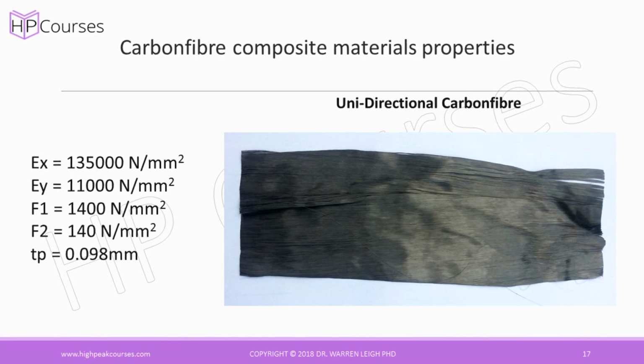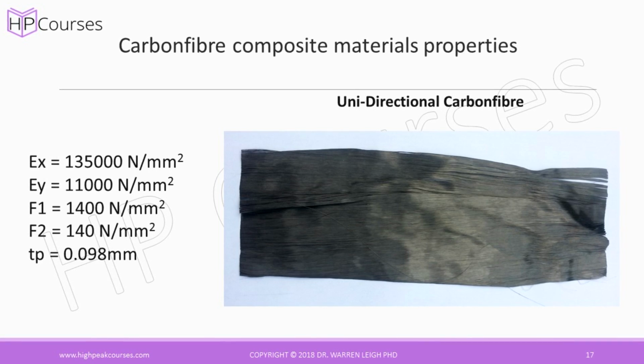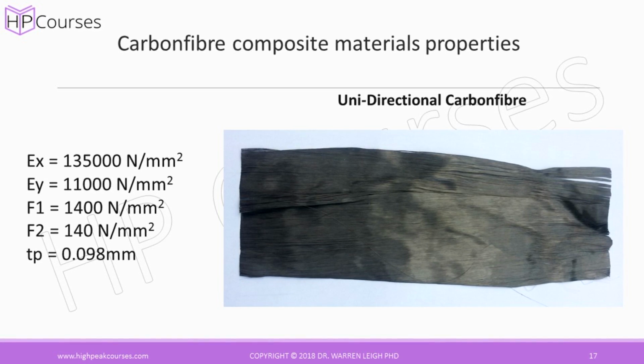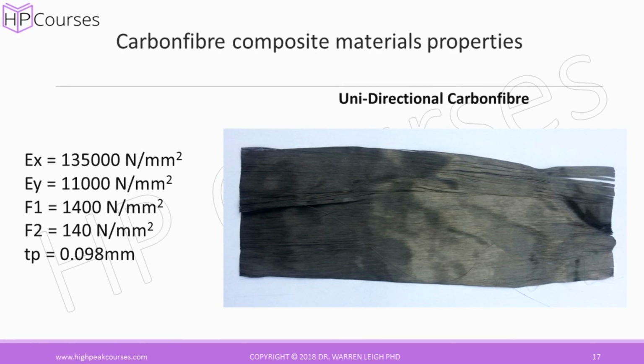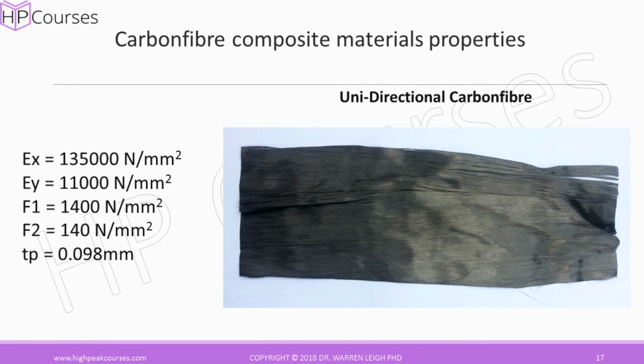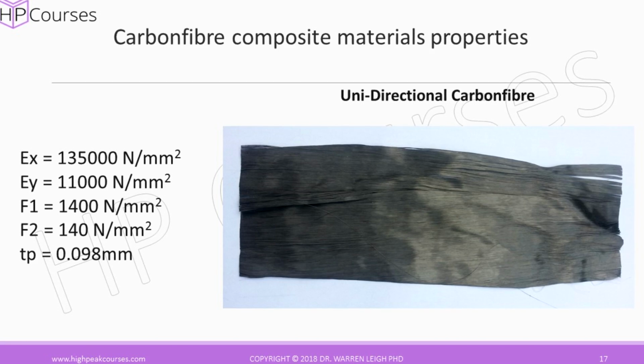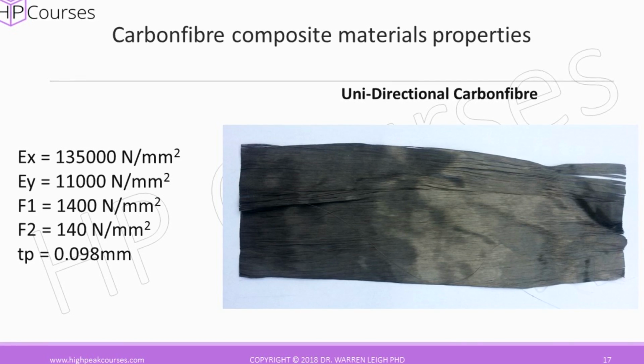Next, we require carbon fibre material properties. I will use published data, and this is embedded in CSAMs. It gives a Young's modulus in the x direction, i.e. direction 1, of 135,000 newtons per millimetre squared, and in the y direction 2 of 11,000 newtons per millimetre squared.